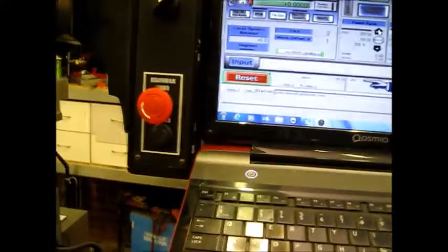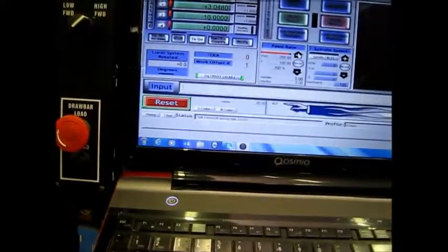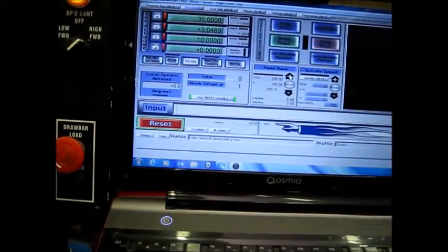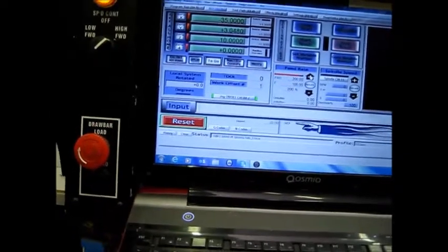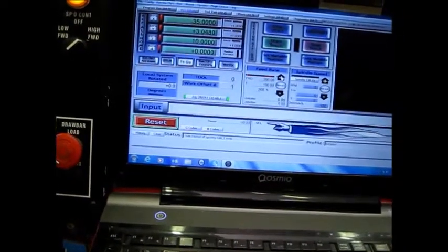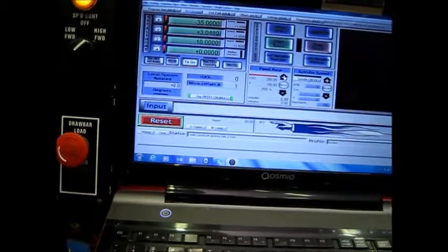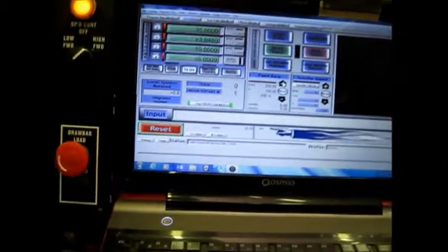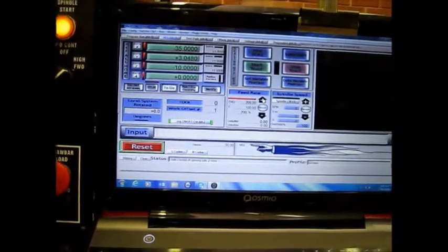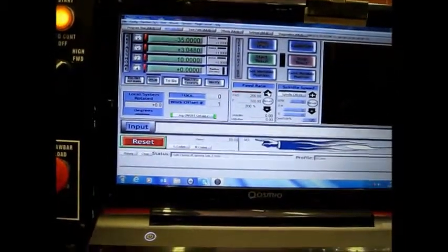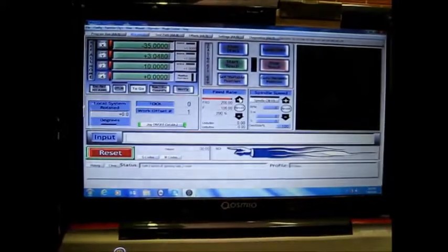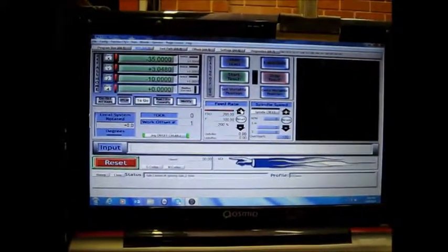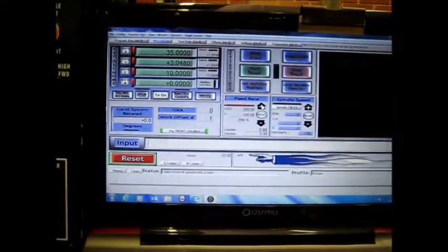Now what I just did then was a problem. I pressed the up arrow key and it moved the Y direction for me, which I didn't want to happen. It was still, the finger was over the feed rate button. I'm going to stop the video there and bring everything back to 0 to resume from where we are.